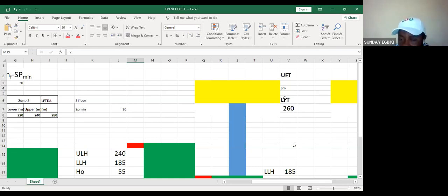But that 2 bar is not a function of the sizing of the height of the tank. It's a function of the pipe that is going away from the tank, which is the distribution pipe. So by tomorrow, Uche will be talking about the distribution pipe, which is the pipe taking water from the tank, and the transmission pipe, which is the one taking water from the reservoir to the tank. Uche will talk more about that tomorrow. Is it okay now?